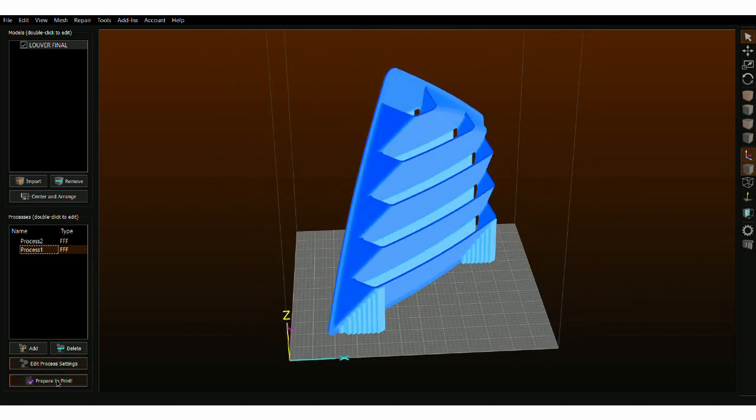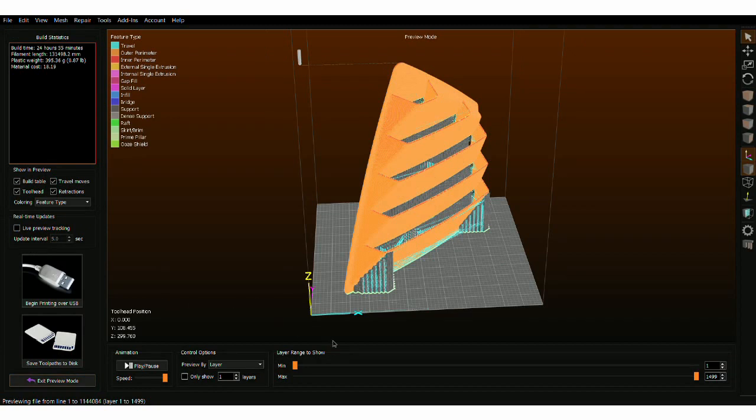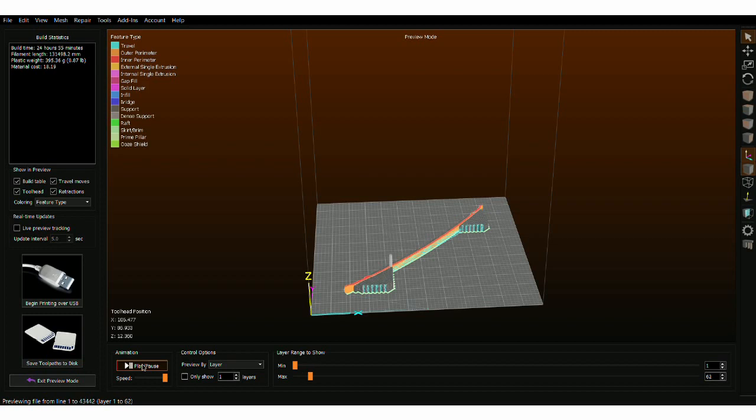I set up the extrusion parameters for ABS plastic as it's the preferred plastic to use for louvers due to its high tensile strength, resistance to physical impacts, and its tolerance for adverse environmental conditions. Once the parameters were set, I added supports, simulated the extrusion path, and uploaded the code to the CR10 3D printer.